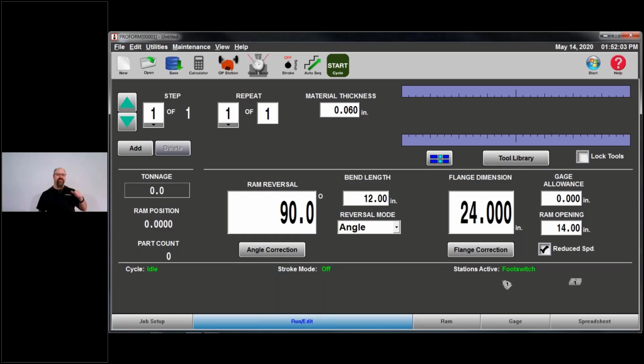Now, it's not often that they can actually modify the DXF, but they will take the DXF from engineering and bring that directly in at the machine or in offline, but a lot of times it's at the machine. And as an operator, I can create my own program knowing, hey, when I make this, I don't bend it this way, I bend it this way and then this way. So it's easier for me to make that call at the machine.